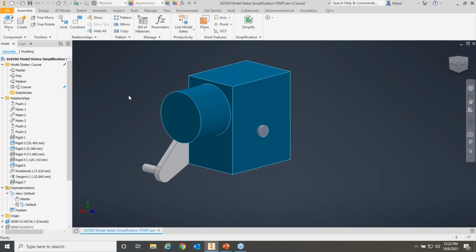And you may even find in some cases, depending on how the parts are used in here, you may have to add additional constraints or maybe offset constraints, maybe to lock something still into place. Like if I wanted this lever arm still to be in the right location, maybe I want to constrain it into place, or maybe I want to ground it into place so it doesn't inadvertently move out of position or something like that. So it really depends on what your end goal is, but just be cautious of the constraints and knowing that you may have to work with those if you remove some type of feature that is used at the assembly level.